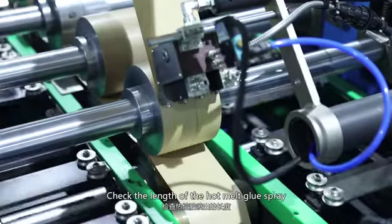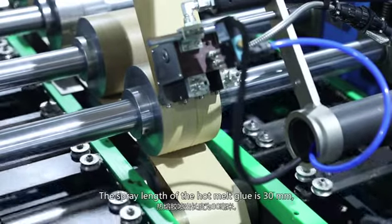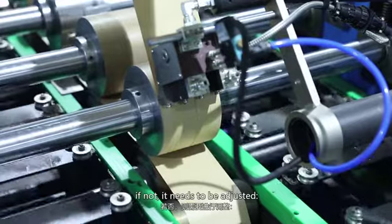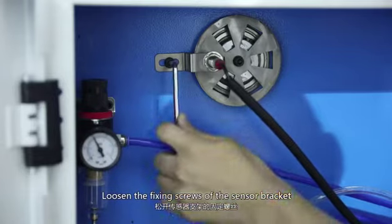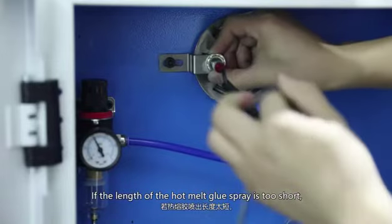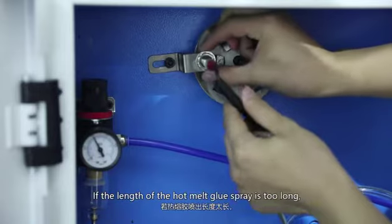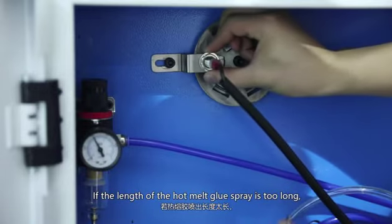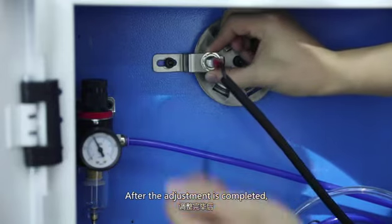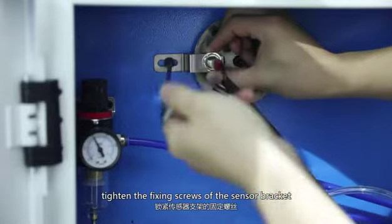Check the length of the hot melt glue spray. The spray length of the hot melt glue is 30 mm. If not, it needs to be adjusted. Loosen the fixing screws of the sensor bracket. If the length of the hot melt glue spray is too short, pull the sensor bracket to the left. If the length of the hot melt glue spray is too long, pull the sensor bracket to the right. After the adjustment is completed, tighten the fixing screws of the sensor bracket.